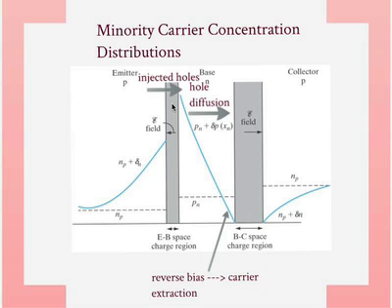This is the diffusion current. Remember, we broke the PN junction into 4 currents: electron diffusion, hole diffusion, electron drift, hole drift. This is just the whole diffusion current. The drift is very small because there's not much of a field inside, right? It's a neutral region, so you wouldn't expect any big, significant field anyway. Okay. This is the emitter base space charge region, which is the depletion region. This is the base collector space charge region, or the depletion region.